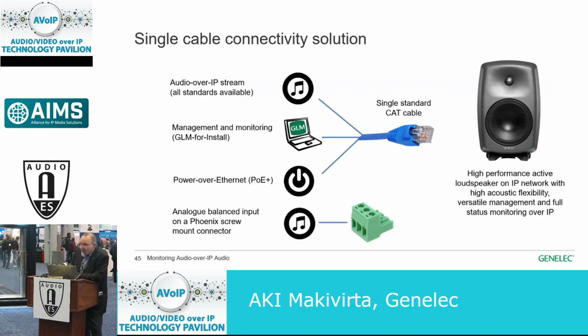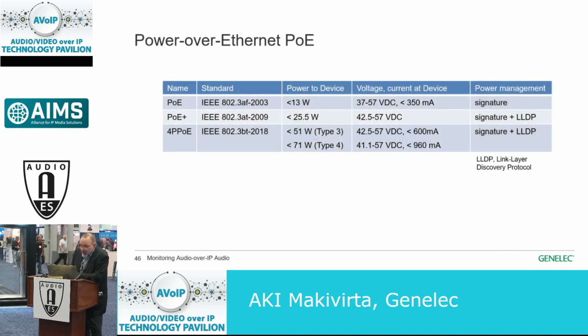What you are provided is a constant rate of input. Here you can see 4 different power levels that have been standardized at the moment for power over Ethernet. We start with the standard PoE at 13 watts into the device. The currently very well available level is 25 watts into the device, and then you have a couple of higher power levels that have been standardized that you can buy into, but they are maybe not so widely being used at the moment in the industry.